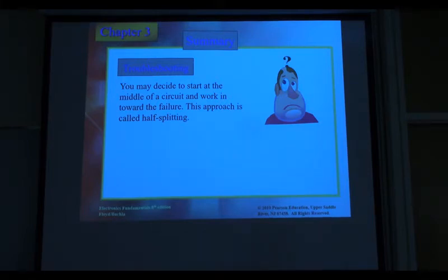You forget the second half and only work on the first one. Then you find somewhere that you can split, not necessarily right in the middle. Maybe this part is for the electric power, this part is for controlling the gain, AGC or whatever. You divide block by block, then you decide. So this is called half splitting. Any questions? This troubleshooting method works for electrical engineering, and also for civil, mechanical, everything. This idea still works, right?